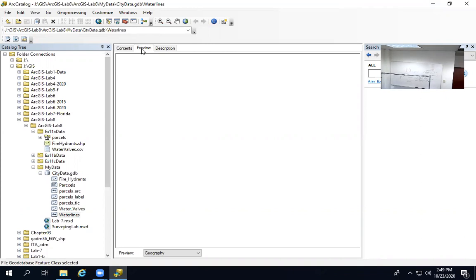Create from scratch. What type of class? You did that already. A field is defined by name, data type, and properties, which are the columns in the attribute table. Also, an attribute domain is a list or range of valid values for an attribute. In the newly added feature class water lines, we want to add the following fields. I closed it already, but I can still fix that.